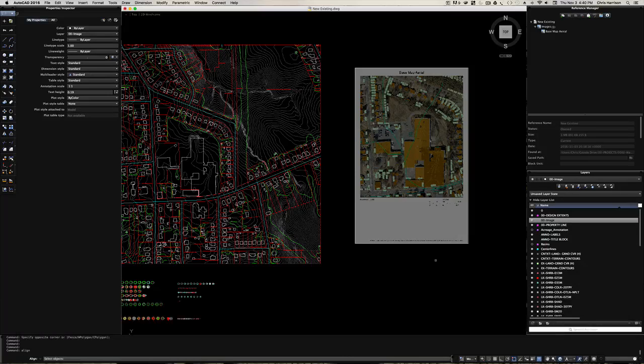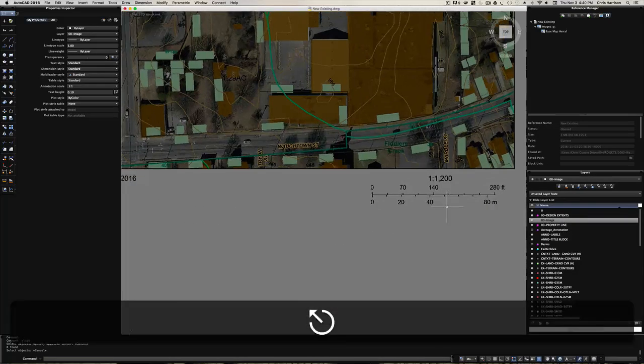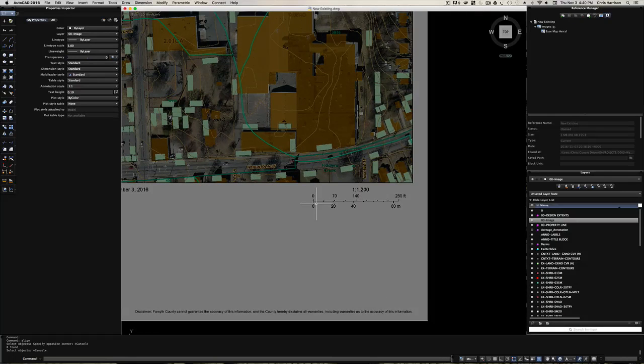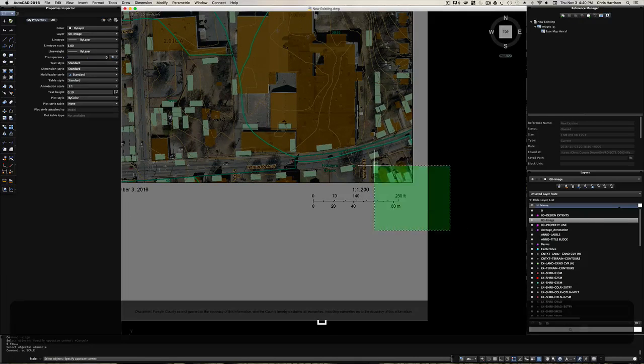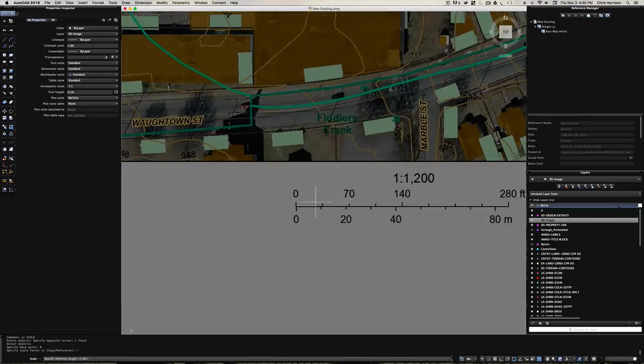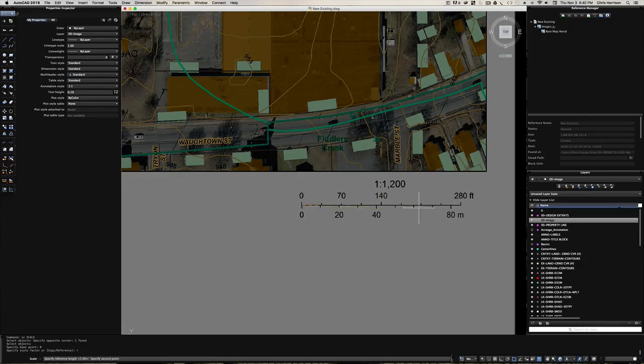So I'm gonna type in a line. Oh well, I guess theoretically you should be able to scale it. It should line up perfectly. Let's see. I'm gonna hit scale, grab this, enter, 0 is a base point, R for reference, and we're gonna zoom in and I'm gonna click here. And I'm gonna hold shift just to kind of align it. Uh-oh, no, it's tripping.